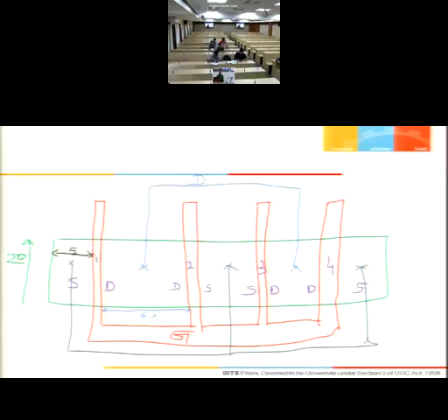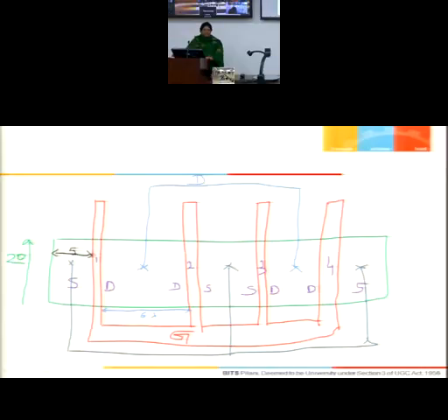Yes, ma'am. So can you visualize what calculations I am making? So total drain area is with me, total source area is with me. It is 240 lambda square multiplied by Cj area plus 24 lambda multiplied by Cj side wall. Compare it with the original values for the 80 lambda single transistor.